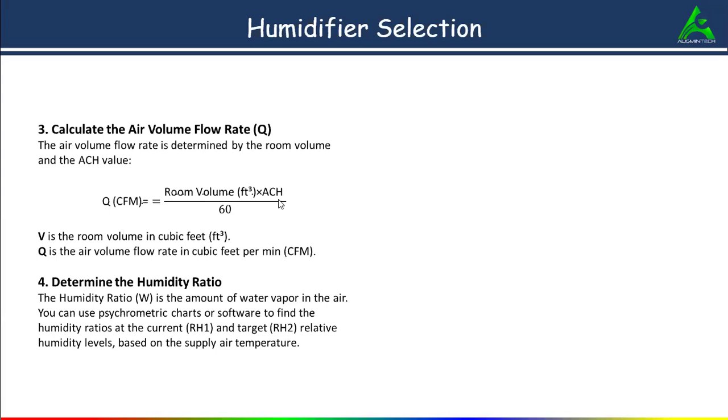The other case is infiltration, like I was talking about. If any kind of crack is there in the wall or roof, there will be air leakage. Or if a window is suddenly opened and high velocity air enters the room due to some condition, like a cyclone, that time a certain amount of heat will gain inside the room.